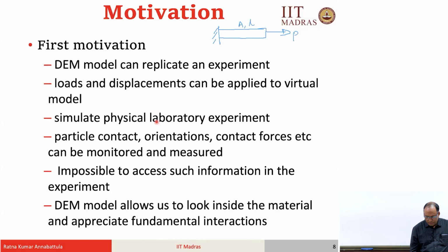And now let us say this is a material having an elastic modulus E. So, let us say this is an aluminum bar. Now, you take exactly the same dimensions, same geometry, everything, load is also the same, A and L are the same, but now it is not aluminum, let us say it is a steel bar. The differentiating factor between the bar being aluminum or steel is its elastic modulus.